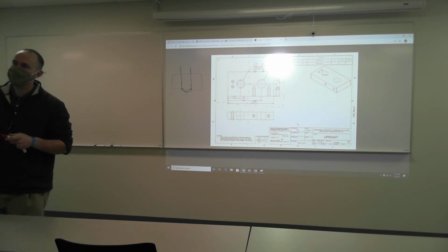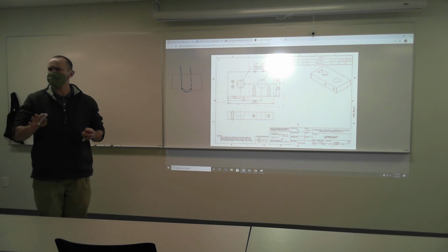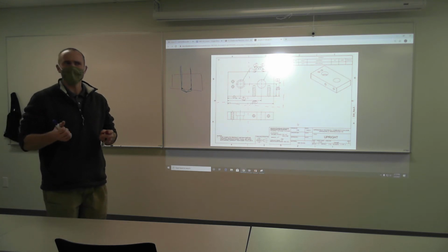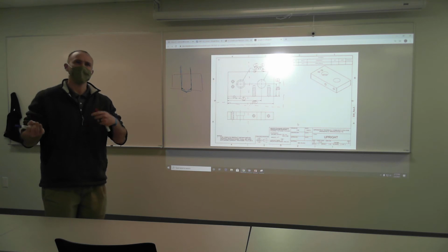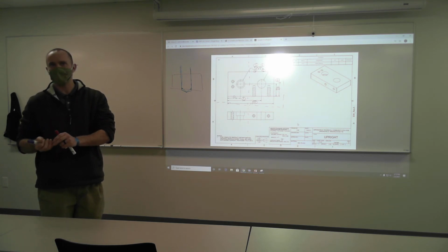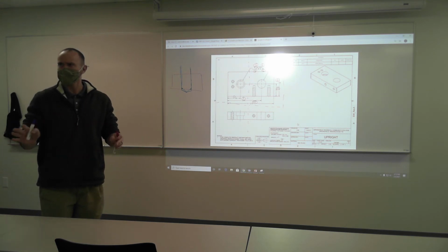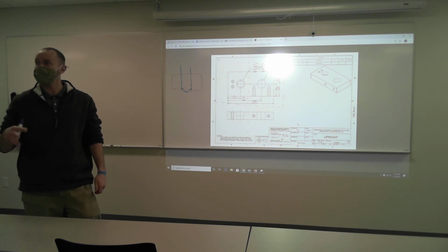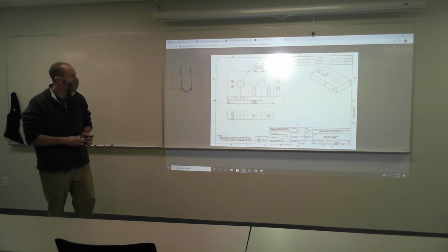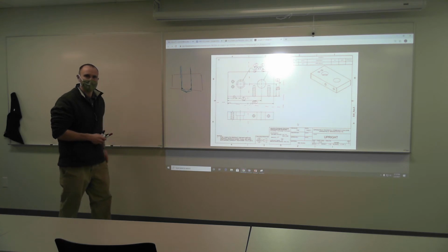The other thing too, it allows us to be more systematic. We don't have to make exceptions like, yeah, we're going to check the depth and diameter of every feature unless it's a through feature and then we don't check the depth. No, that's too much thinking. We're going to check the depth and diameter of every single feature and then we don't have to worry about exceptions. So that's why we would want to check that through condition separately.